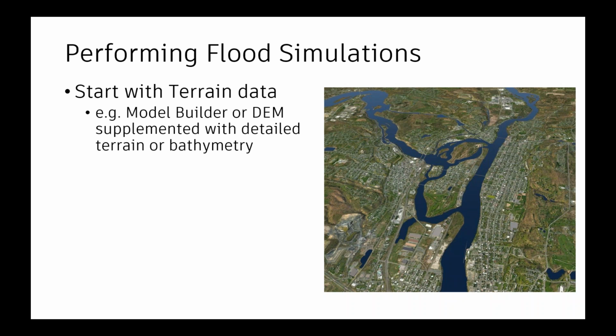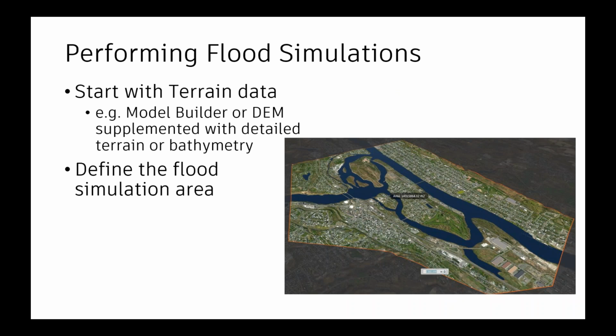Most of the DEM and model builder data, you'll see the water surfaces are actually modeled as terrain. So for a more accurate model, you'd want to include the bottom of the water surface elevation. The examples I'm going to do are large historical flooding events, 10 times or so larger than the average flow, so it minimizes the error there, with that larger difference.